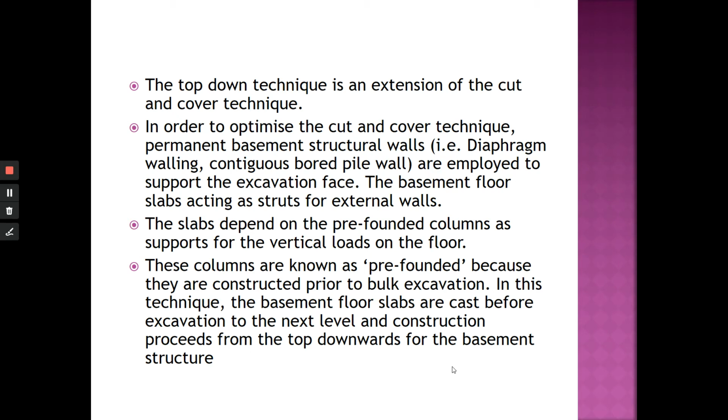The slabs depend on the pre-founded columns as support for the vertical loads on the floor. Okay, of course, columns support vertical, beams support horizontal loads. Okay, these columns are known as pre-founded because they are constructed prior to bulk excavation. They are constructed before the excavation, okay? In this technique, the basement floor slabs are cast before excavation to the next level.